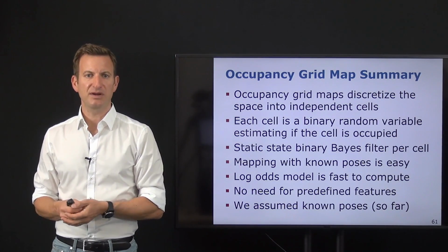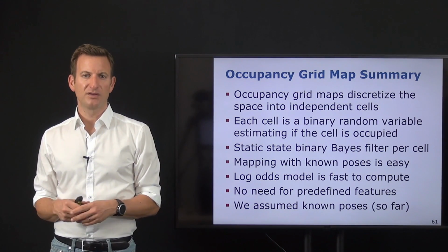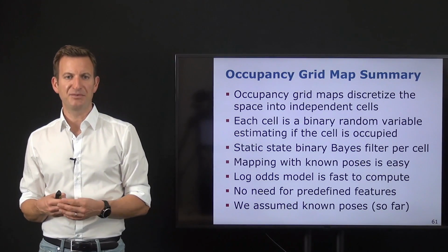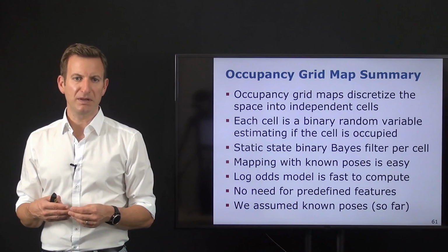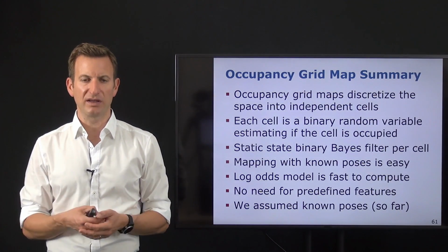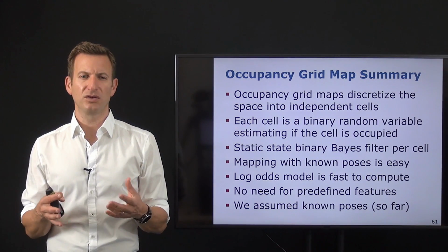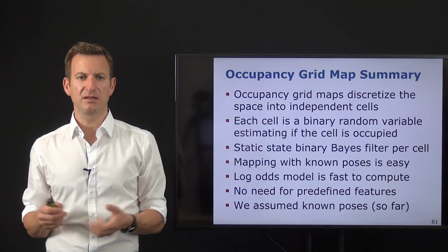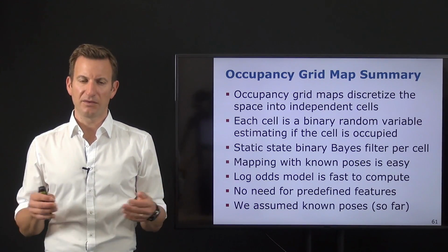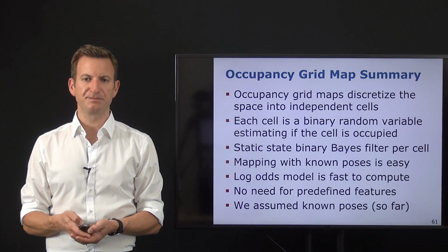The only thing I'm suffering from if I do this in 3D typically is that the memory consumption grows substantially, and maybe I don't have enough memory to store larger maps, and so things may get a bit more complicated. You can have optimized data structures such as octrees or octree-inspired implementations in order to store your points, so you maybe don't want to estimate the whole grid as a 3D array, but in theory the same thing we've done in 2D can also be applied in 3D.